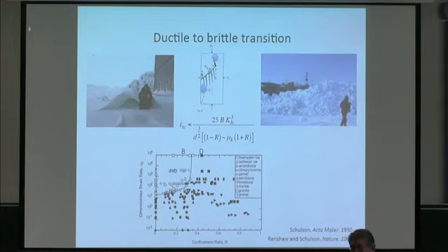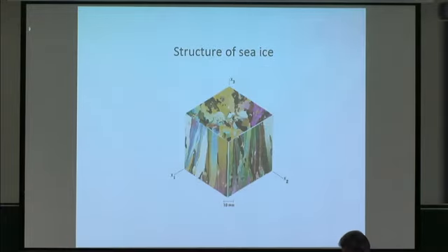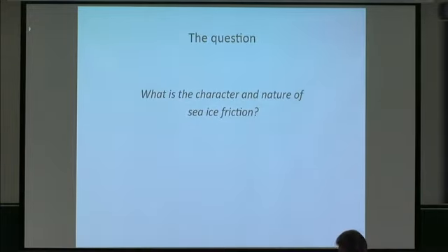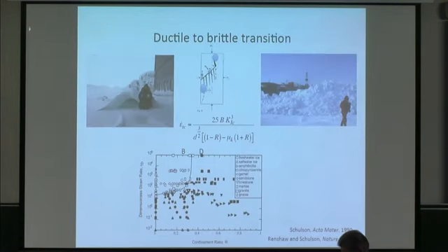Again, in terms of that same model, but this time one simply invokes at the tip of the secondary cracks a creep zone, which if large enough, blunts the crack so that the overall behavior of the material is ductile, whereas if that creep zone is smaller than the elastic strain zone, fracture continues, the crack grows, the material exhibits brittle behavior. The transition is when the creep zone size and the fracture zone size are about the same.